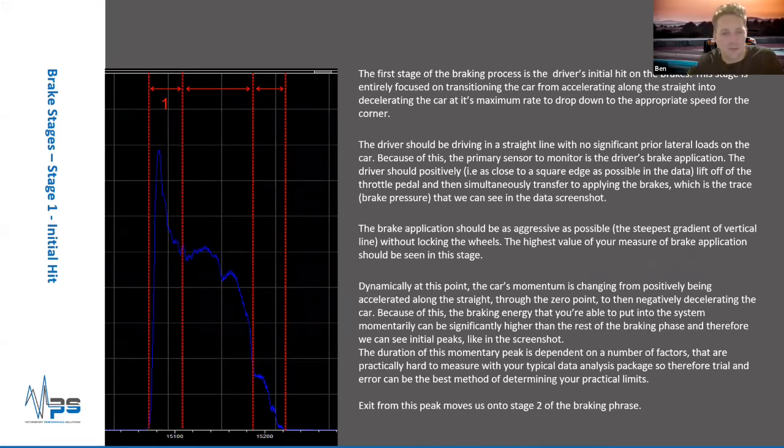That's what we're looking for when we start to analyze our data. When I've worked with a lot of amateur drivers, what we typically tend to see is this peak, the highest point. So we expect to see the highest brake pressure, highest brake applied force, should always be in this first phase.